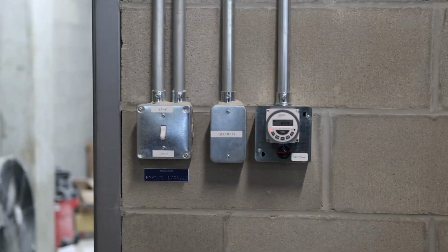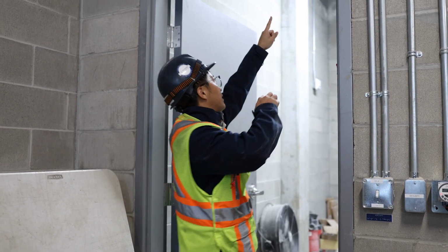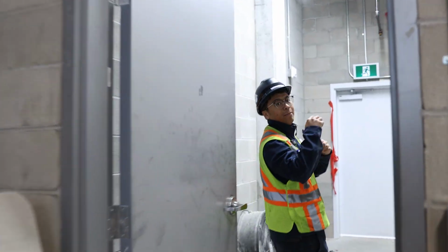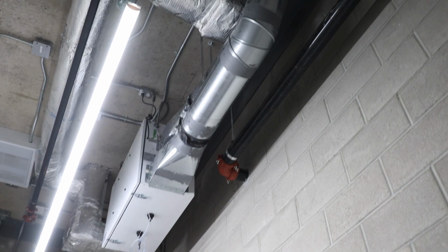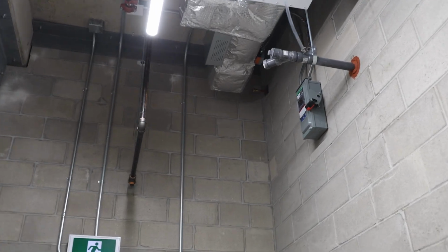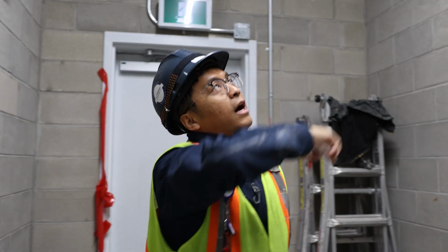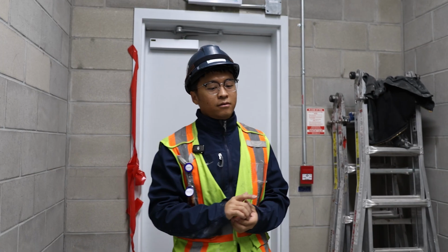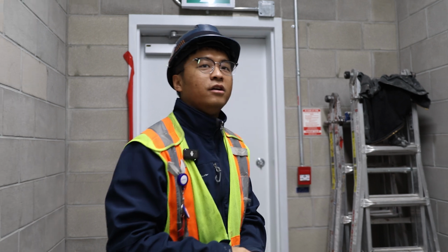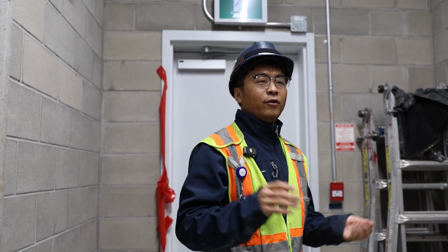HRV1, it won't open. The fan won't start until the damper fully opens. I can show you where the dampers are. That's one of the dampers. This is the other one. This will be the fresh air, outside damper with the electric heater. And that's our exhaust damper. See, the HRV1 is still not on, because it's waiting for the actuator. It's waiting for the damper to fully open. Now it turns on because the damper fully opened.